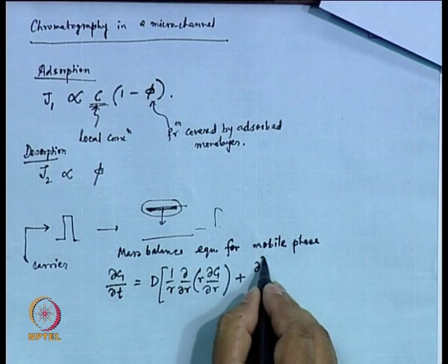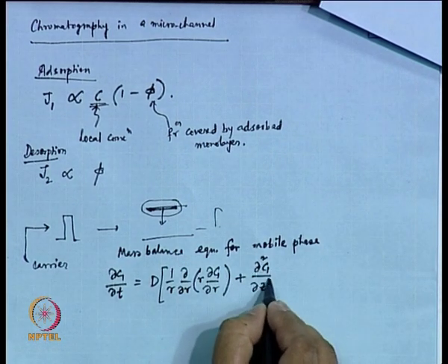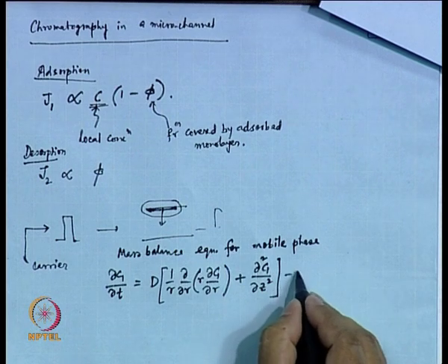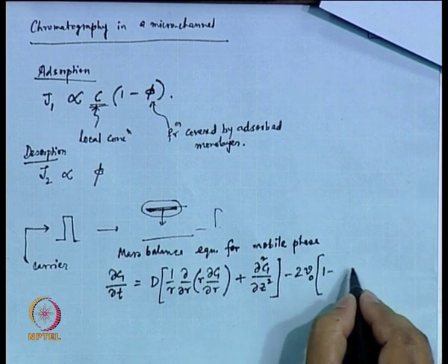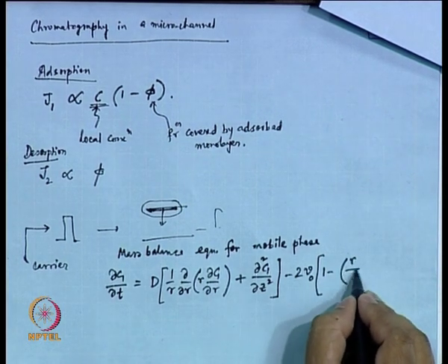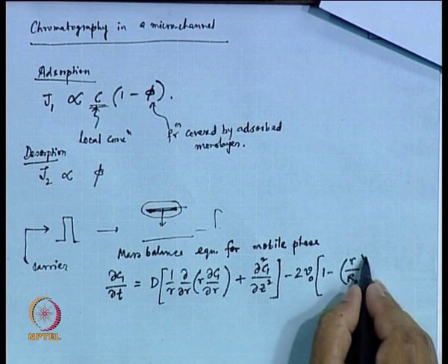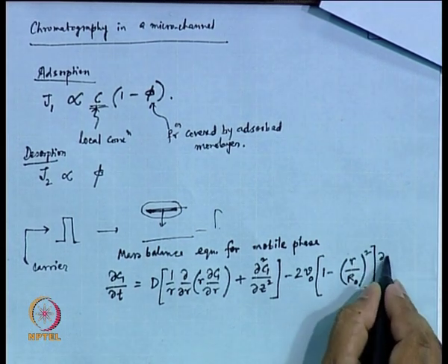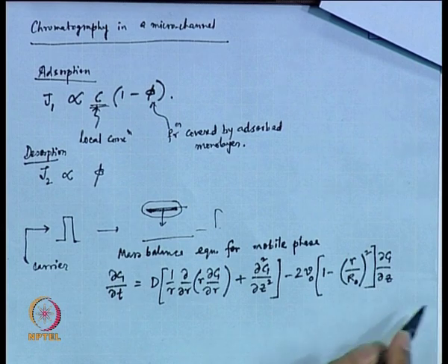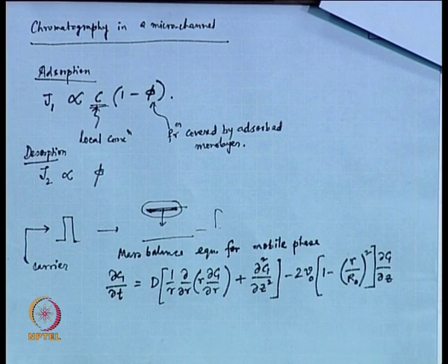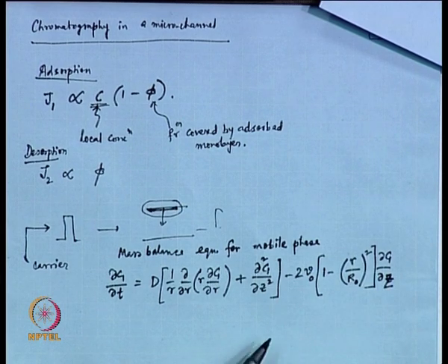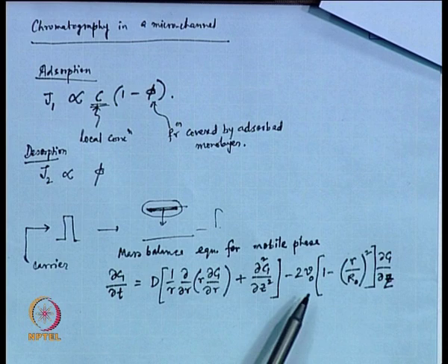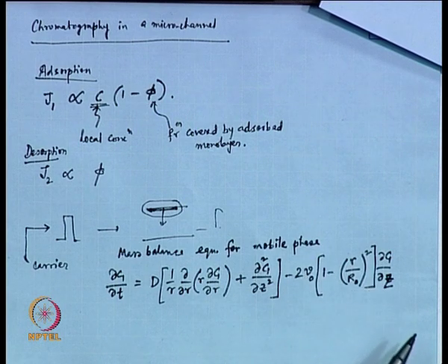The second term is a new thing we are talking about, an axial diffusion. If you have a long channel, probably it is wise to have the axial diffusion also considered. Earlier, in the case of Taylor dispersion, what you considered was basically the axial convection and radial diffusion. Here, this is that axial convection term, the velocity term V del C del z, still there.